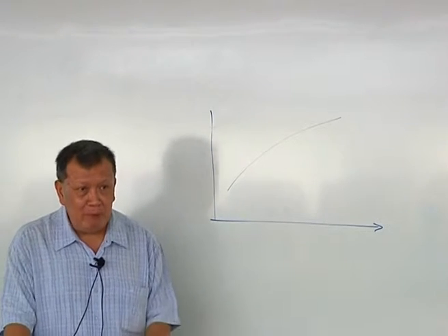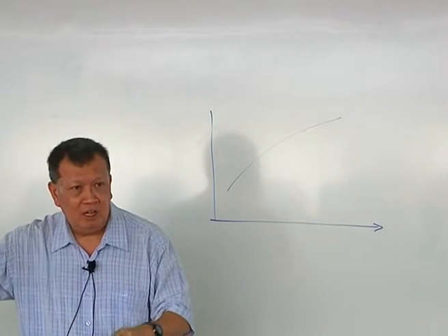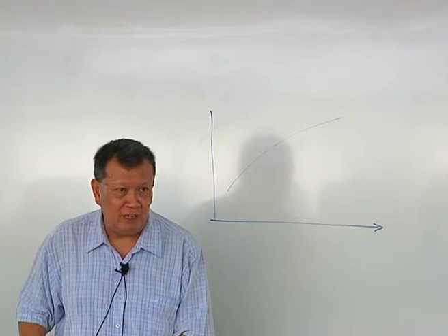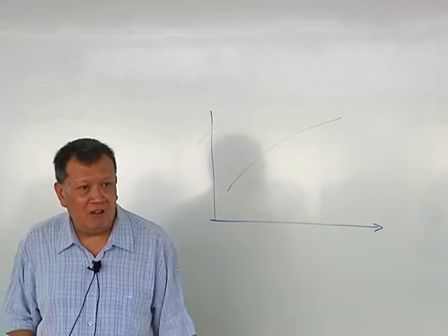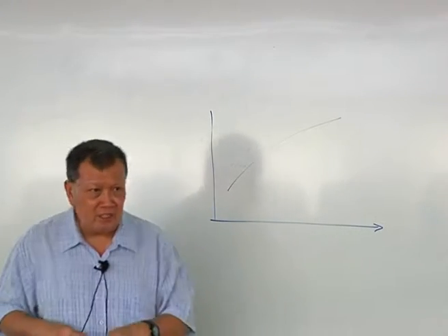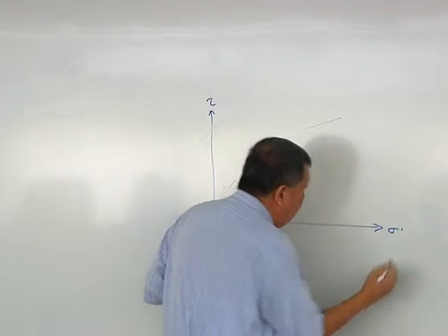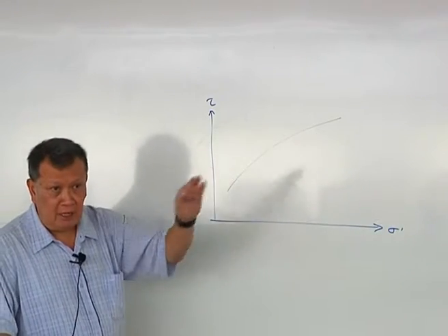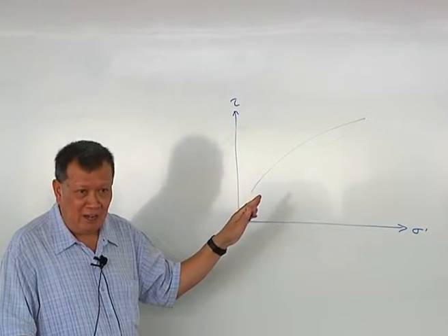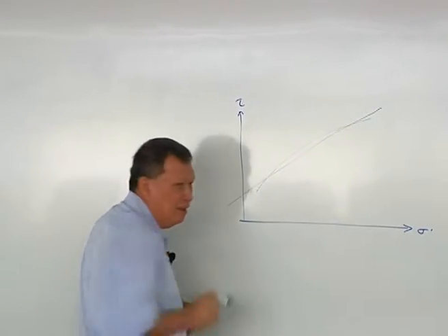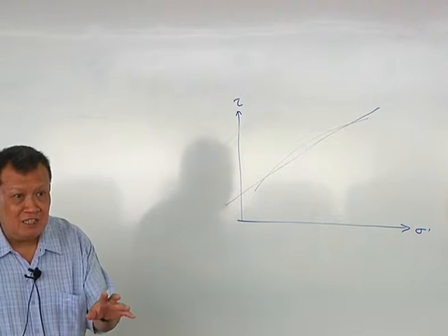That's why there are people who, for the same 3 Mohr circles, if I give it to you and I give it to him, you probably end up with a different set of c' and phi'. Because he may take the first and the third circle and you may take the first. You're not wrong, he's not wrong. You know what I mean? But the important thing is that when you look at the failure envelope, it's actually like that. But engineers don't like a curve. They like a straight line. So I easily just project it back. This is the reason why they idealize it to a straight line.